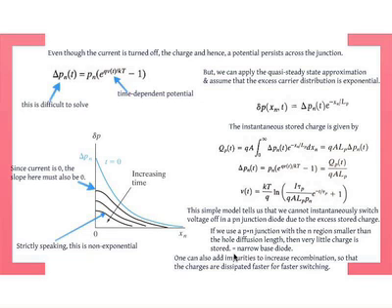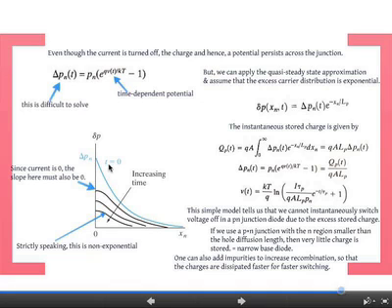Impurities create energy levels within the band gap. Then impurities will create some states inside, which allows an electron here to essentially come down, a hole here essentially, and fill a hole here. It increases the probability of this recombination event happening. This hole, this electron, basically combined. Okay? So you can do all kinds of tricks like that.